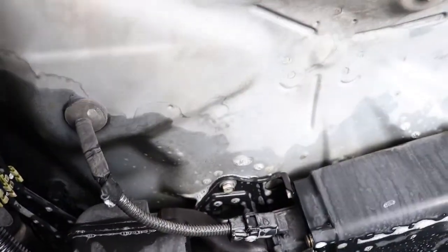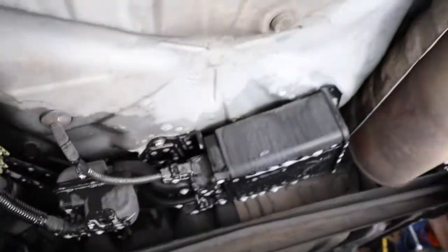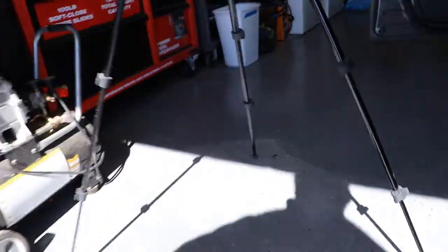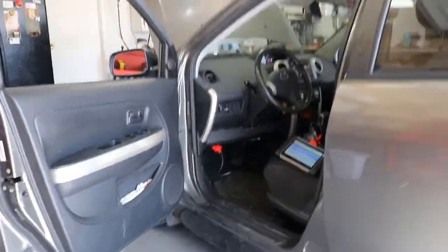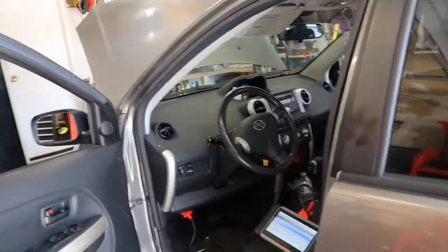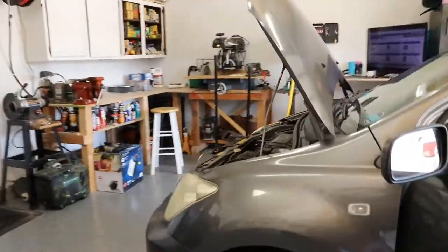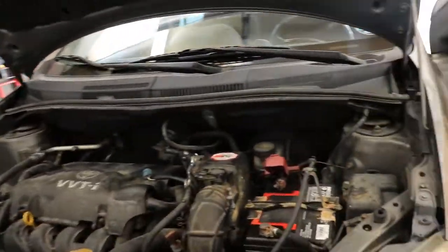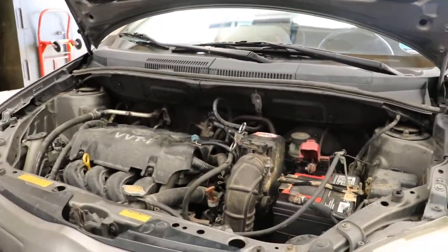So our main issue is coming down to that front solenoid, and maybe that front purge valve solenoid wire, just the connector, and maybe even the hose here at the bottom, which I'm going to replace for sure because it is cracked pretty heavily and probably is leaking. So that's the diagnosis. So I've come down to it.